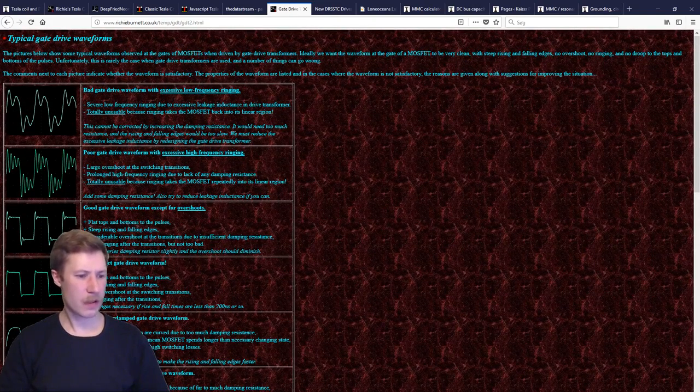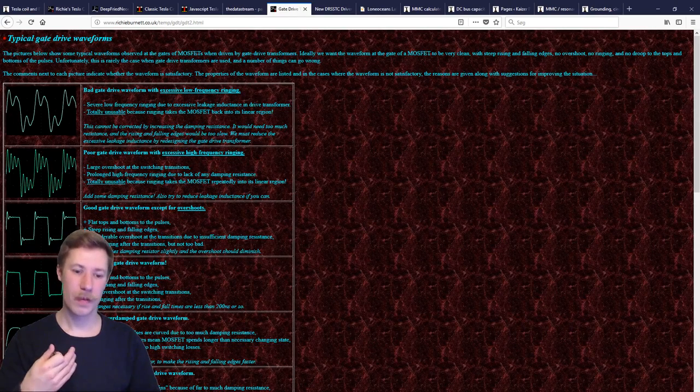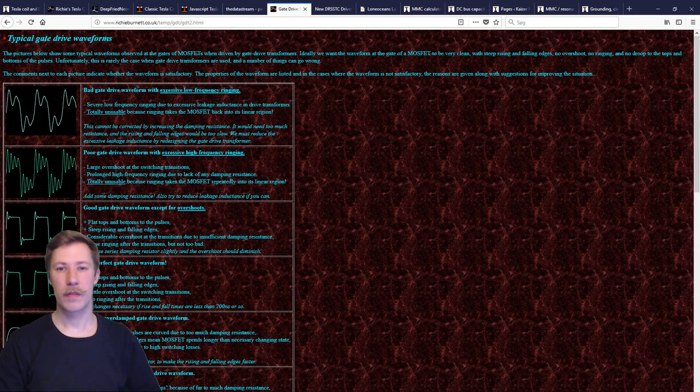Okay, Arpad asks, should the resonant frequency of the primary/secondary be measured with them in place or not? Yeah, you should assemble your coil as it would be standing when you have it running, because the proximity of the primary coil to the secondary coil will affect the resonant frequency of the secondary coil. So everything that is near the coils, and the proximity metal objects and so on, will all affect the resonant frequency of the secondary coil.